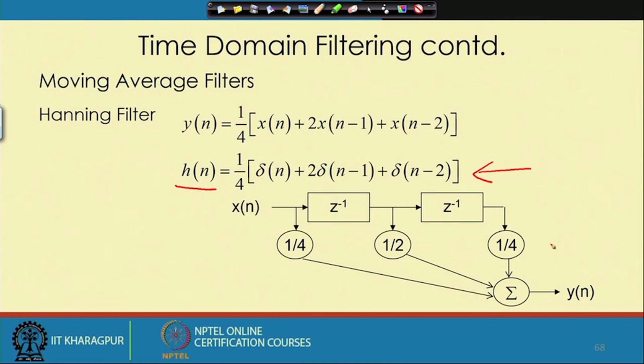But if you implement it in a computer, it is better to use shifting, and if required, if you have odd values, you may have to use multiplication. But integer multiplication is much faster, and in the case of an integer filter, that is the advantage we take to provide the result in real time and with cheaper hardware. That means we can use, say, a DSP, which is an integer DSP, to do this job.